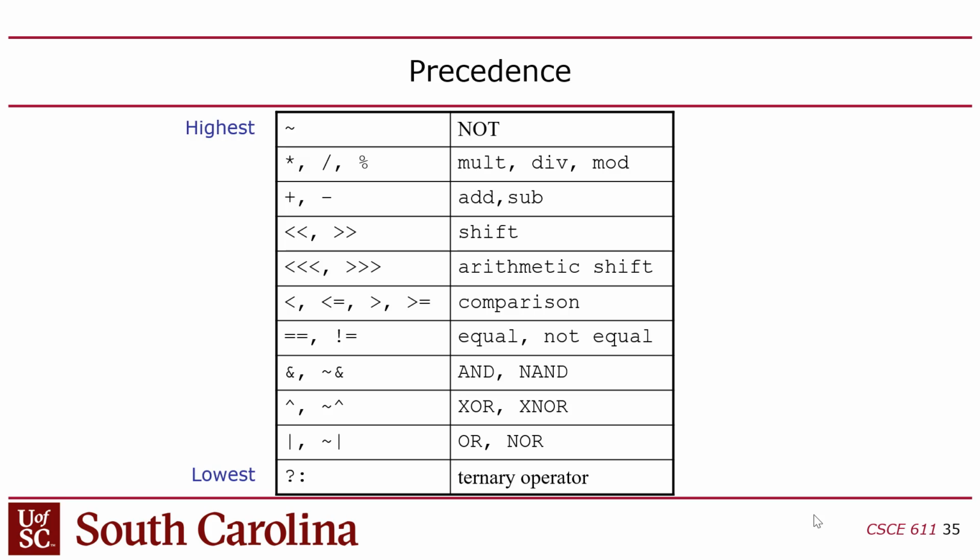Now, the equals equals and bang equals also have counterparts that are equals equals equals and bang equals equals. The difference is that the first ones are intended to be synthesizable, which means that if you have two signals in your simulation that are both Z, which is high impedance, and you test them for equality, the answer is false.